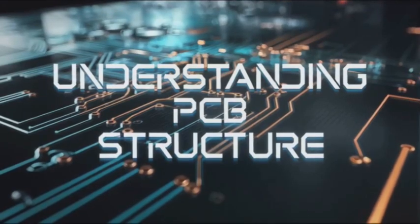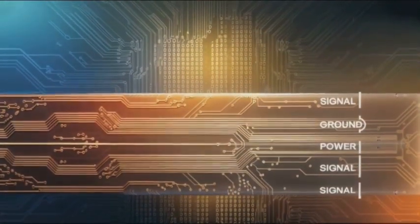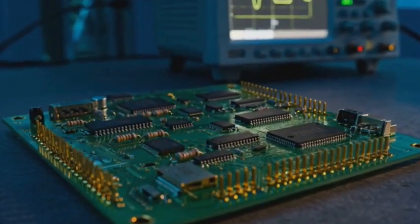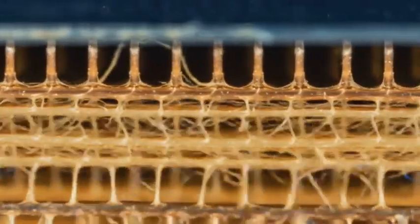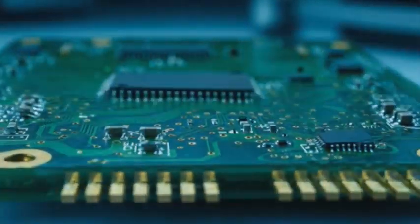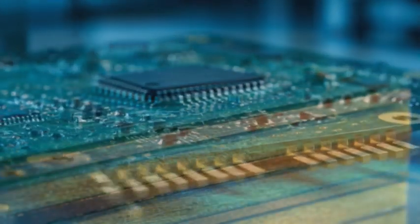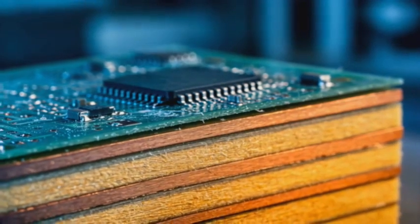Understanding PCB structure is fundamental. A typical 4-layer board stacks signal, ground, power, then signal again. Internal layers usually handle power and ground, separated by dielectric materials like FR4. The outer layers carry signal traces, with core thickness typically larger than prepreg layers, influencing EMC performance.